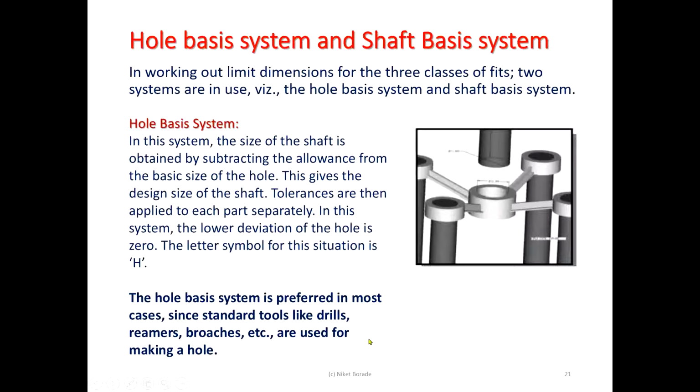Okay, there is another way of making the hole, which is you drill the hole and then you do the internal turning. Then you can change the internal diameter to any number. That is possible, it is not impossible, but generally it is not a preferred way because it is not an economical way of doing it. Also, internal turning cannot be applied for small diameter holes, right? It cannot be done.